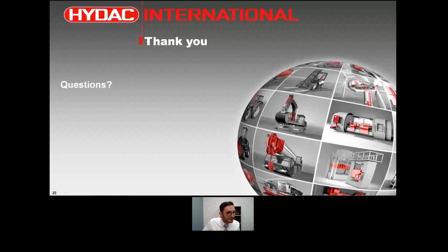Andrea Chimodoro asks: Does HYDAC know the difference in accuracy between a pressure transducer using standard IO connection and IO-Link? The accuracy will be just whatever the sensor has. On the data sheet, it will tell you the accuracy of the pressure sensor from the physical world to the analog conversion, and that's the only thing they can define, because everything beyond that is out of our scope, in terms of what cable is used or anything like that.